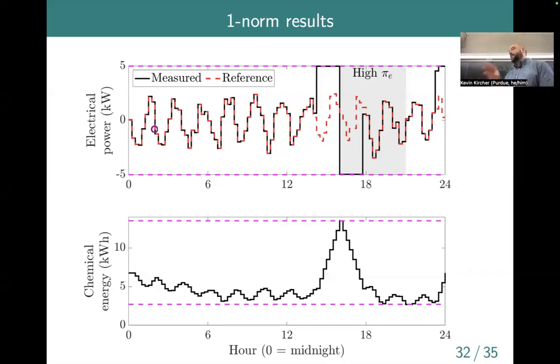So we send out a signal every second or 2 seconds, and we say, use 10% more power, use 15% less power. And it typically varies in this kind of sinusoidal fashion. And that's used to basically do this continual balancing of supply and demand. So that's kind of what we're emulating here. In reality, we'd be using like a 1 second time step, not a 15-minute time step for that problem. But this shows roughly the shape of the problem. Does that make sense? Okay.